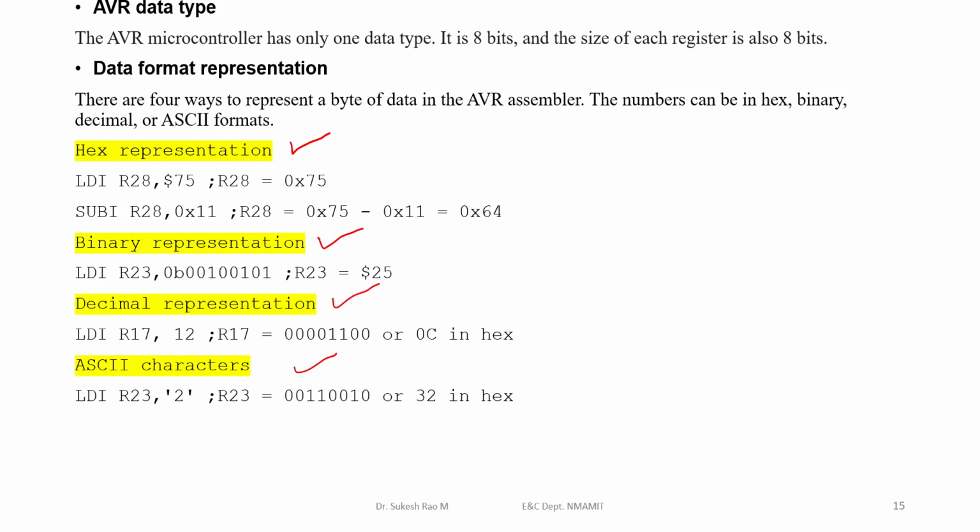Another representation is decimal, where you simply write the number. Remember, if you are loading any register, let's say LDI R16, and I say 25, then it doesn't mean that I'm loading $25.